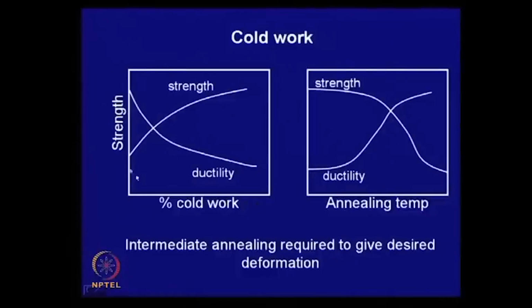So, if you have to give a very large amount of deformation, often it may not be possible in a single stage. After giving some amount of cold work, you may have to bring down the strength, otherwise the load required to deform will be very high, and the tools available with you may not be able to give that amount of deformation.